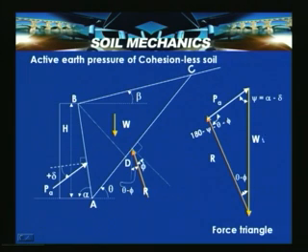So, this is by solving this equilibrium, and as we discussed, one of the demerits is that the equilibrium conditions are not satisfied. That means that when these forces are acting, they are non-concurrent. At least two forces will try to meet, and the third force will deviate from that point. So, despite these differences, because of the merit in which the theory has been formulated, it has got an edge over other theories. Though it has this demerit of not satisfying the equilibrium conditions completely, it is widely used.